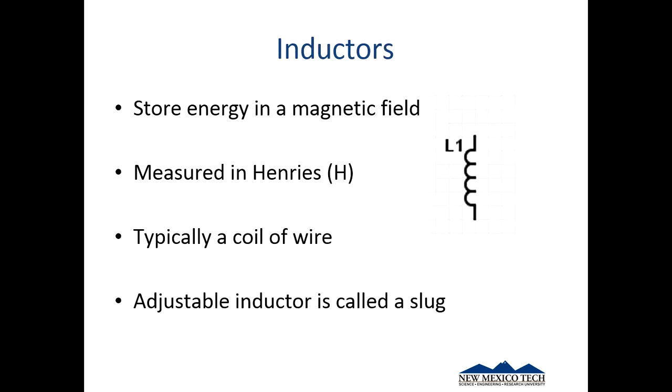So that's one way you can do that, with a wire or with an inductor, lots of ways you can do that. Maybe you've got a tap that runs part of the way down, and as you turn the knob, it just slides along here and picks a different spot. That's an adjustable one. Anyway, bottom line is, in general, an inductor is a piece of wire that has a coil to it. And as it turns out, all wires are going to have a little bit of inductance, and they're all going to have a little bit of capacitance, but that's okay. We'll deal with that later on.